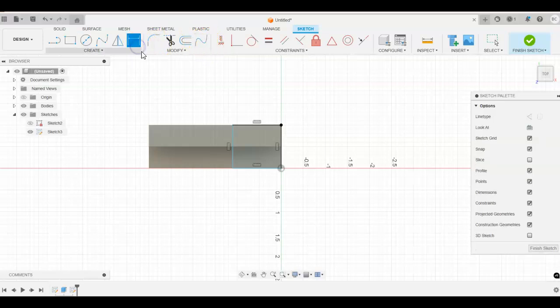Let's go back in and add some dimension tools here. We know, according to the activity and the drawing in the book, that the dimension from here to here is 2 inches, so we're going to set that at 2 inches. Now, I don't need to add a dimension on this vertical y dimension here, because when we created our geometry, I selected that point and went down to this line.